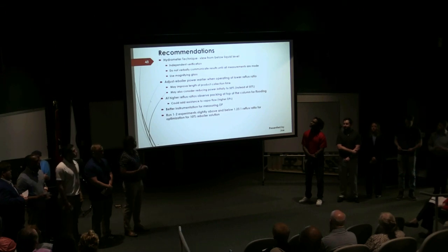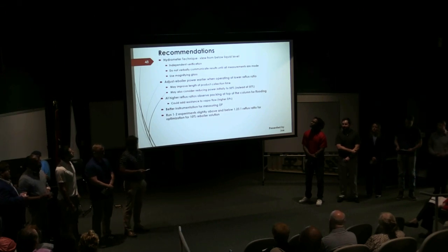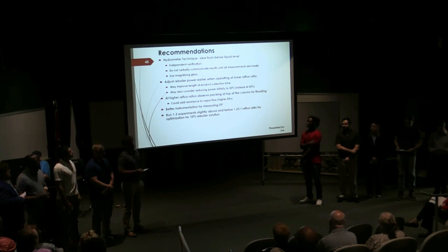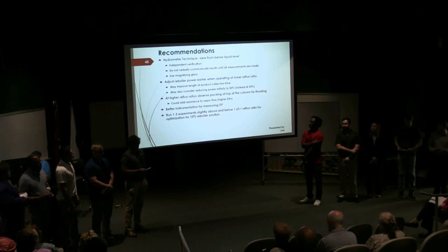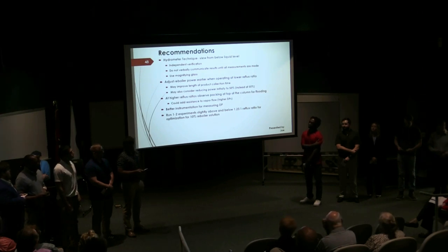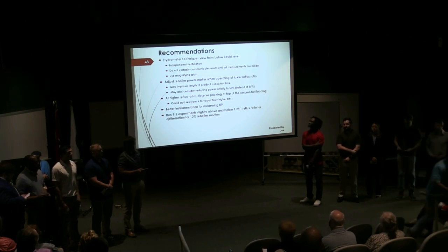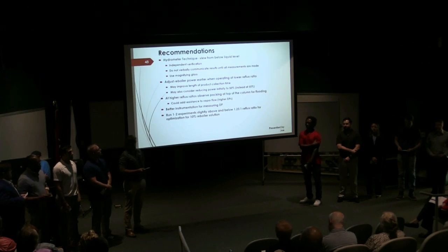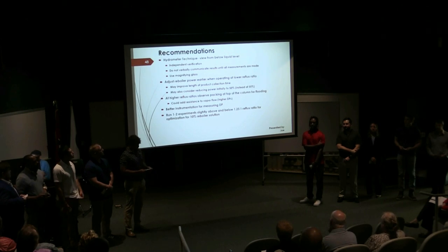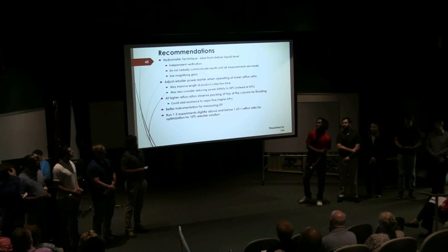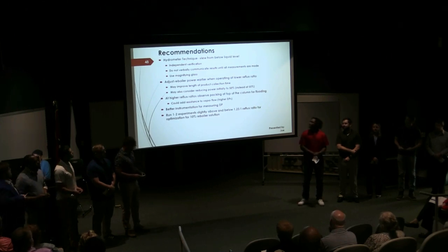Based on these results, we came up with these recommendations. First is to improve lab techniques, use more than one person for verification, increase reboiler at half a degree instead of 1, maybe consider using a lower reboiler power on our first adjustment, and we should observe the top of the column to check for fluid. We should also optimize around 1.25 to 1 reflux ratio for 10% solution.